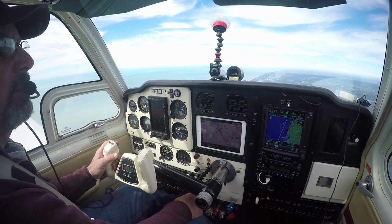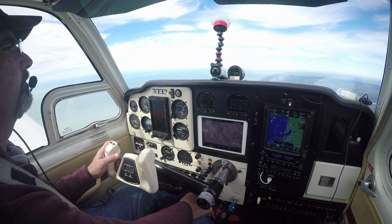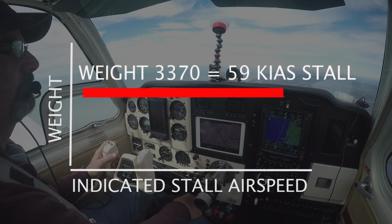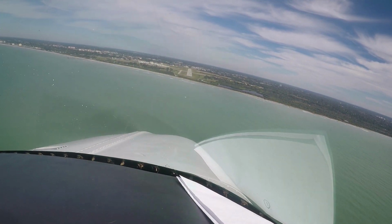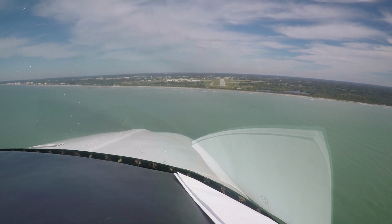Let's take a look. First of all, you probably know that stall angle of attack is independent of weight, but indicated stall airspeed isn't. The lighter the airplane, the lower the indicated stall speed, with some exceptions. What that means is that when the airplane is light, the airspeed can be adjusted downward with the same stall margin. Most of us don't do that, so we end up flying approaches a few knots faster than necessary. Too fast approaches are more likely to result in too fast landings, and those can get ugly. And even if they don't, they use up more runway than is really needed. That matters if you're trying to do a short field landing.